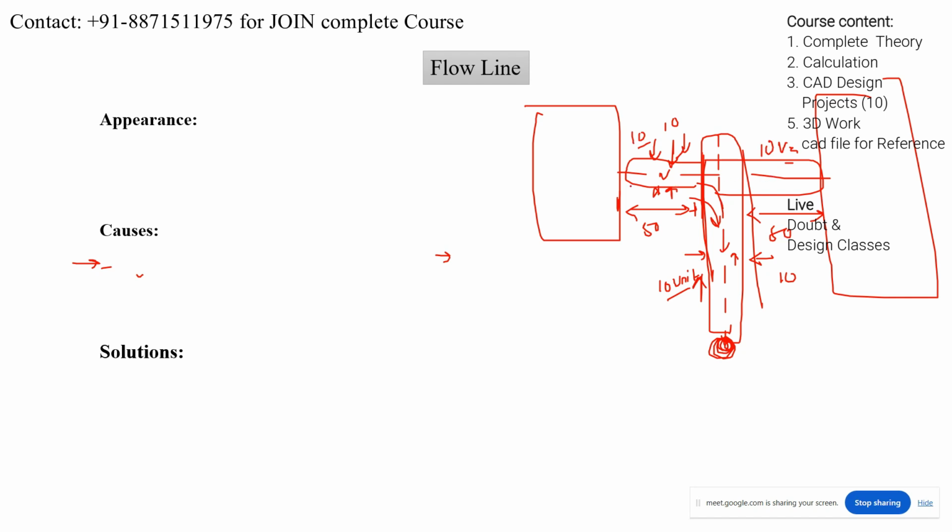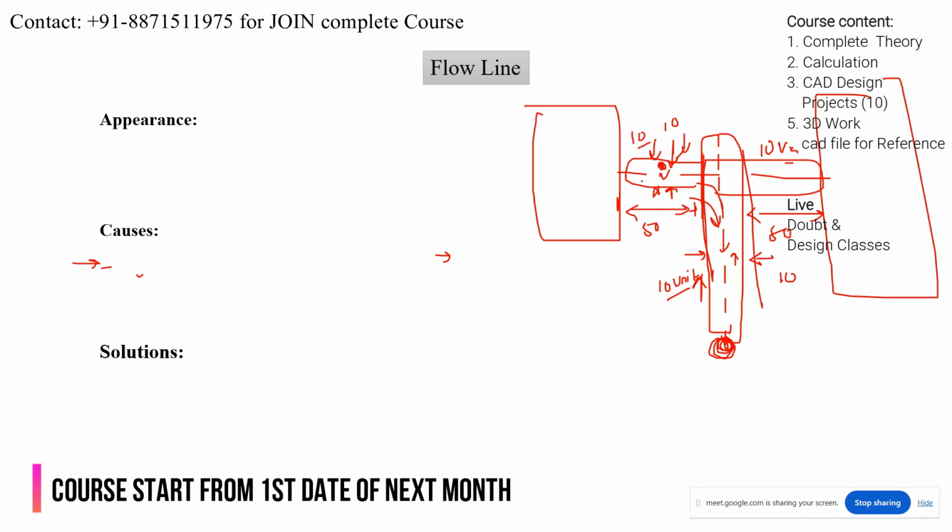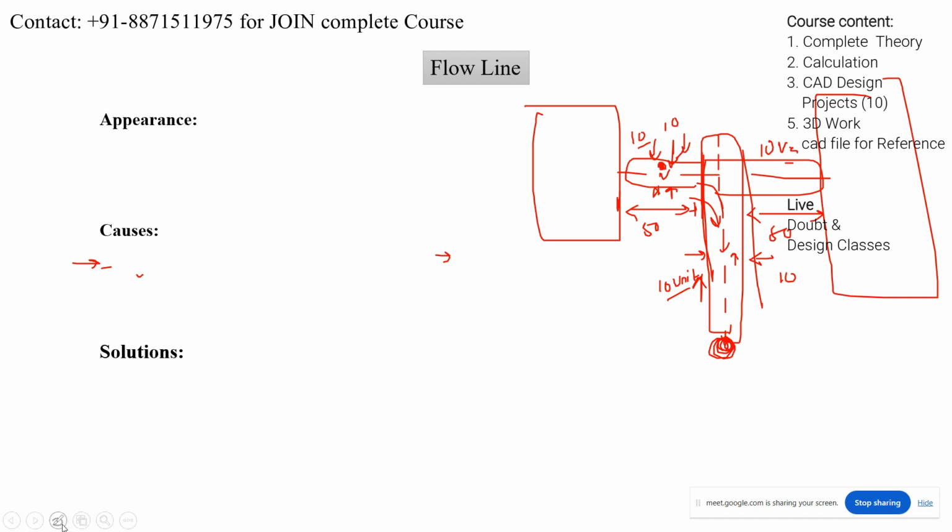So, for example, if the velocity decreases here, because of that flow lines will occur. Maybe there is a possibility of that. Is it clear? Okay. Because there will be cooling variation. Because of the speed, cooling will be higher here, and here cooling will be less.